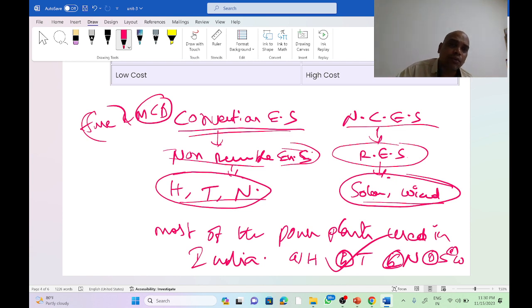But coming to MCB, you can switch on again. No need to replace the copper lead. That is the main advantage. Because by using the knob, you can switch on again in MCB, but in a fuse, it is not possible. Time taking. But here, you can switch on instantaneously. And this one is based on overload, it will damage. The fuse will melt out. But coming to MCB, it automatically shuts off. Here you will use the relay.